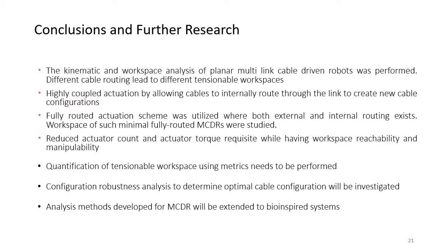In conclusion, the kinematic and workspace analysis of planar multilink cable-driven robots was performed, and different cable routing schemes were proposed, which led to the different tensionable workspaces. Highly coupled actuation by allowing cables to internally route through the link to create new cable configurations was presented.